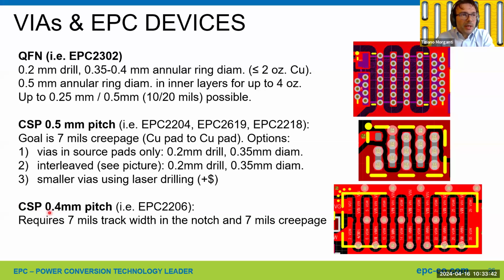Regarding our chip scale package with 0.4 millimeter pitch, an example EPC2206, this is even more challenging, and most likely the standard vias cannot be placed in the pads.